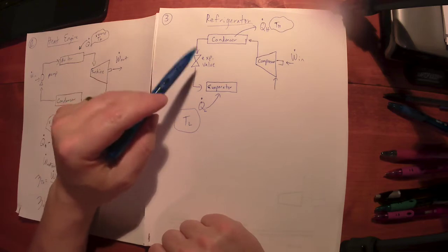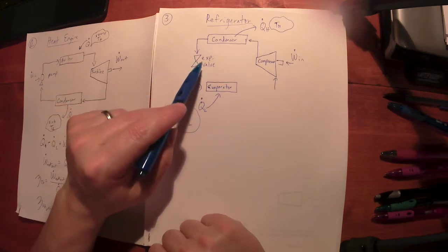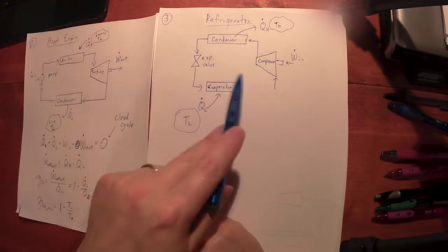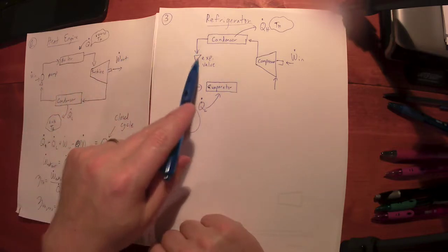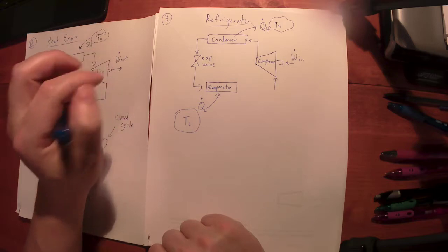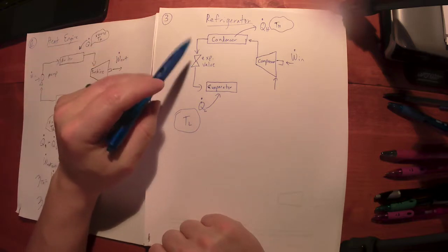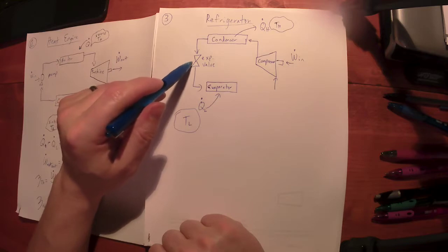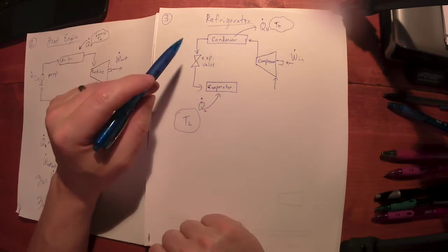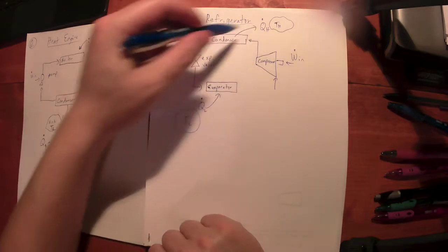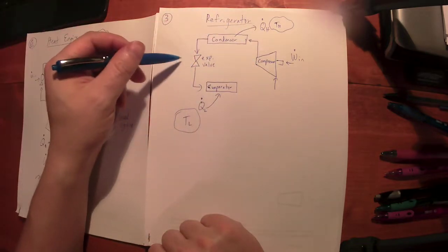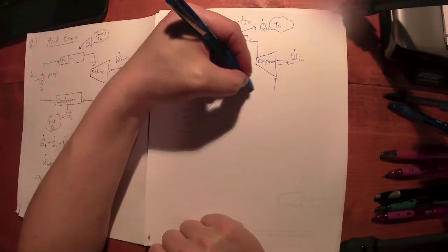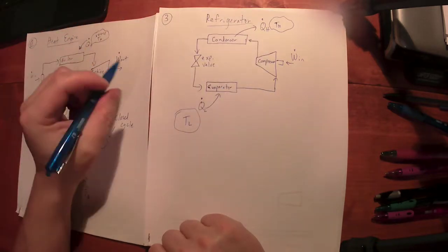You could use a turbine here. I think we talked about that. If you use a turbine here, this actually is the exact reverse. You see that in really large refrigeration units. In your household refrigerator, you don't want additional moving parts to fail, and you're not going to generate that much electricity off of a turbine in here, but you could put one in there. But again, if I'm moving massive amounts of heat, putting a turbine in there and extracting a little bit of work out to power some small devices would actually be pretty cool, and we see that sometimes.